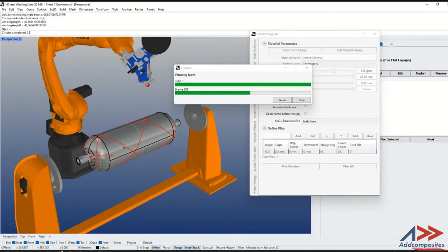That basically ensures that you would have the placement of the tape in the right direction. And you can manipulate each of these frames. So let's say in a certain section, if these frames are in a way that your robot will hit something, you can actually go and change this set of frames that basically tells the robot to tilt in a certain way to avoid an obstacle. So it allows you a very high degree of customization for this program that you create.